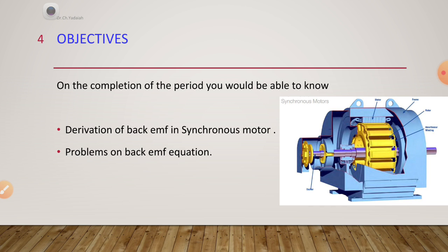During this period, the motor works at synchronous speed. Once the rotor is rotating at synchronous speed, the relative speed between the damper windings and the stator field is 0, so the induced EMF in the rotor damper windings is 0, and it now works as a synchronous motor.